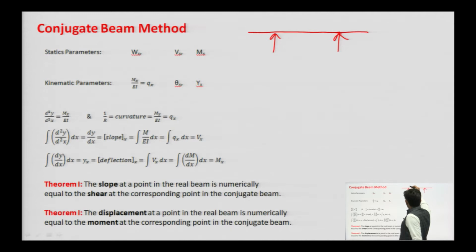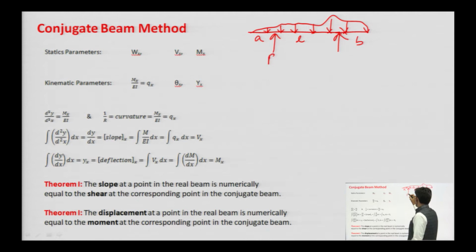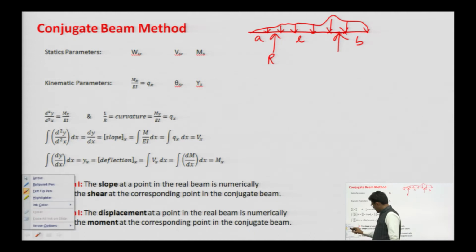Say this has a certain type of loading, any type of loading that it can carry. Depending upon the load value and different values of lengths, say L, A and B, the reactions can be calculated. After calculating these reactions, we can plot the bending moment.